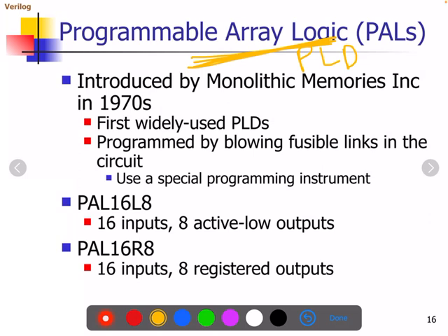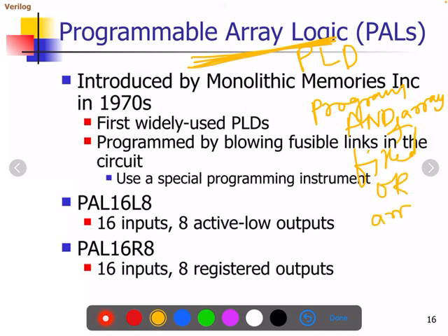Programmable array logic has a programmable AND array and a fixed OR array. That means at the input side, the AND gate array has programmable pins. At the intermediary level towards the output side, the OR gate pins are not programmable. That's why we call it a fixed OR array.